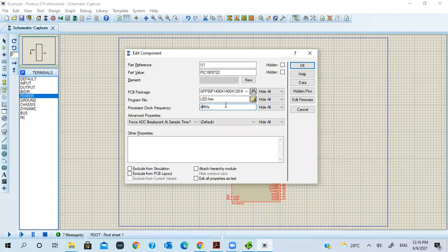So what happens to the time? It is inverse. We are expecting a time delay of 1 second, but in this particular case we are decreasing the frequency by 5, so the time will increase by 5. Though our program says we need to generate a 1 second delay, our time delay will be increased to 5 seconds.